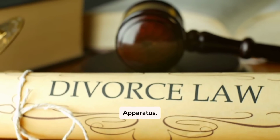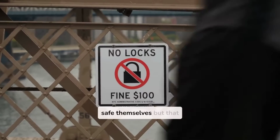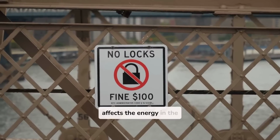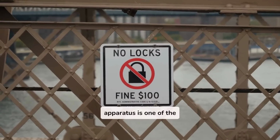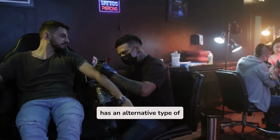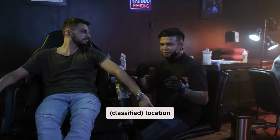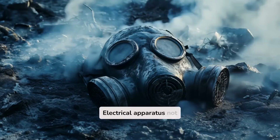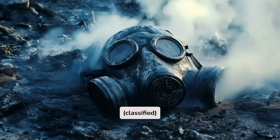Associated apparatus. Apparatus in which the circuits are not necessarily intrinsically safe themselves, but that affects the energy in the intrinsically safe circuits and is relied on to maintain intrinsic safety. Such apparatus is one of the following. Electrical apparatus that has an alternative type of protection for use in the appropriate hazardous, classified location. Electrical apparatus not so protected that shall not be used within a hazardous, classified location.